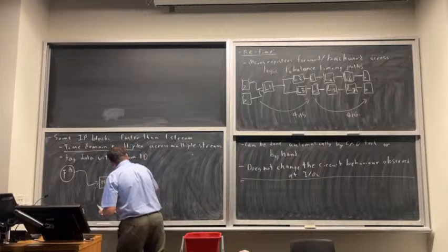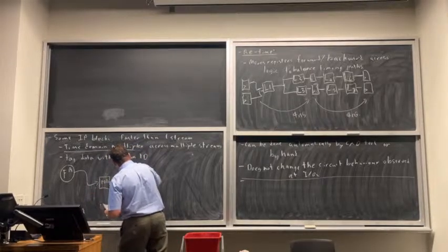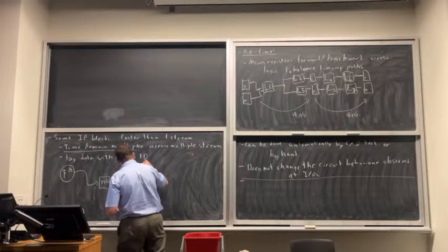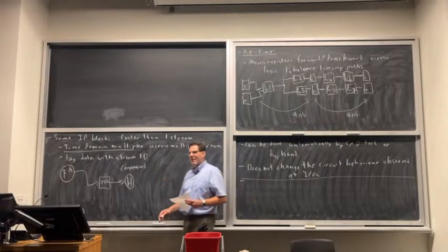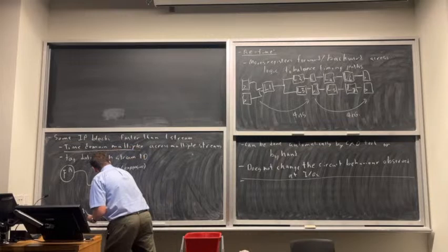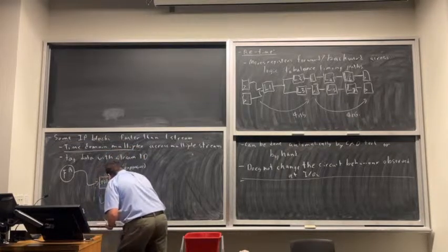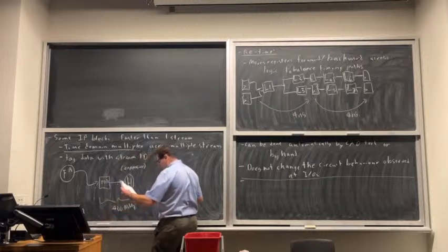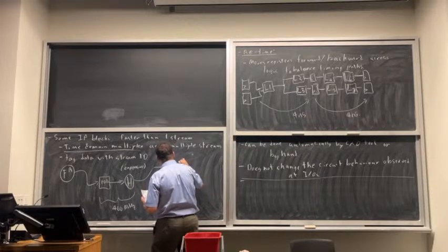I use an IP block, and let's say the IP block's pretty expensive. So maybe it's an FFT. Pretty big IP block, heavily optimized by somebody. I bought the IP block from them, or I got it from Intel or Xilinx. And this is really well designed, runs at 400 megahertz. So this was done by a better designer than me. Then it goes out and it's going to go into a FIFO.